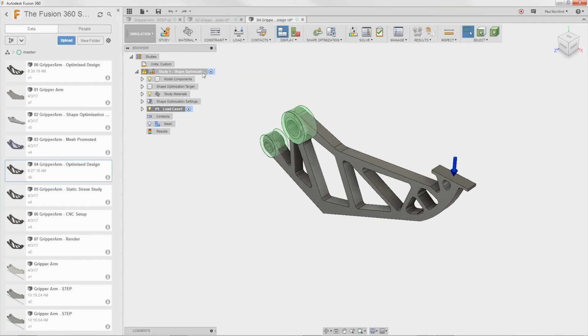So I'll create an extrusion, and just notice I didn't need to sketch in that last boundary. Fusion will pick that up for me, and then I could cut this material away and say OK. So you can see how we can use this mesh to reference, to better remove the geometry which we've analysed and decided is not needed in this design. Now, I won't sketch out the whole thing, so I'm going to take you to one I prepared earlier.